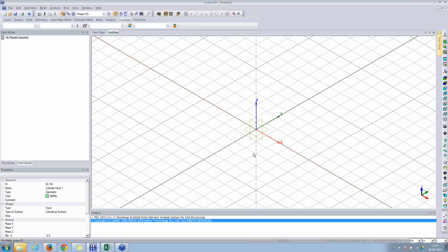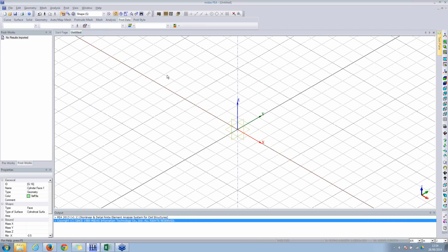If you model anything as plate elements, you will be able to extract forces, local forces directly. As we saw just a few minutes ago, for steel, we were able to get local forces. Okay, and for solids, we only get stresses. So you will have to use different techniques to calculate the forces, bending moments, etc. from the solid geometry.